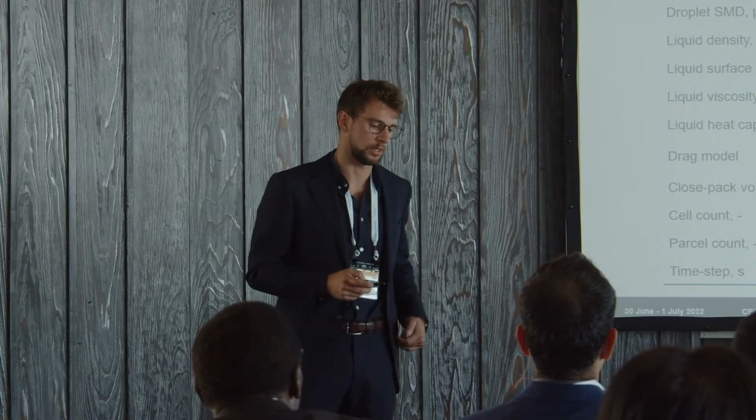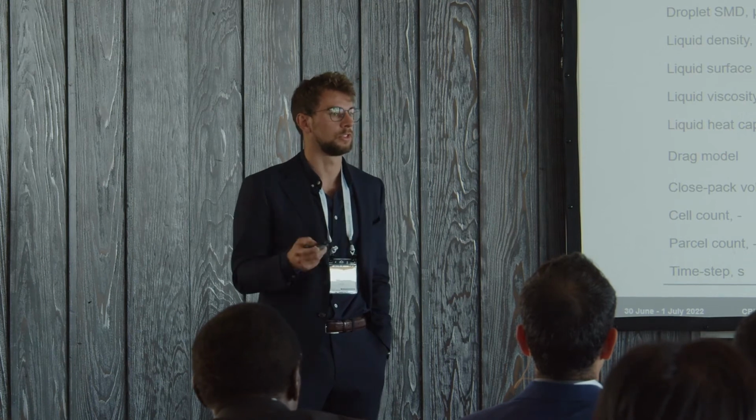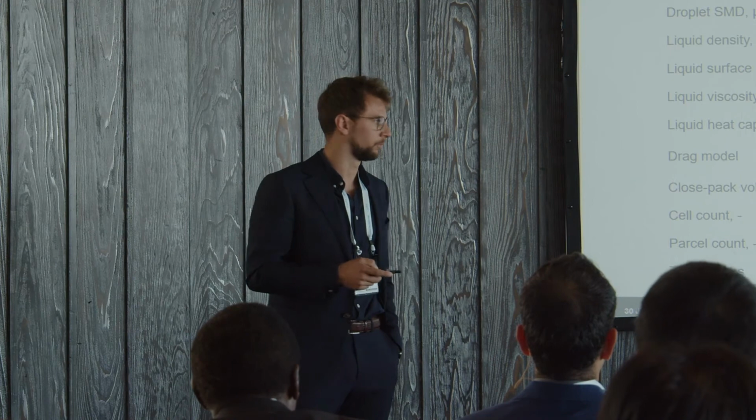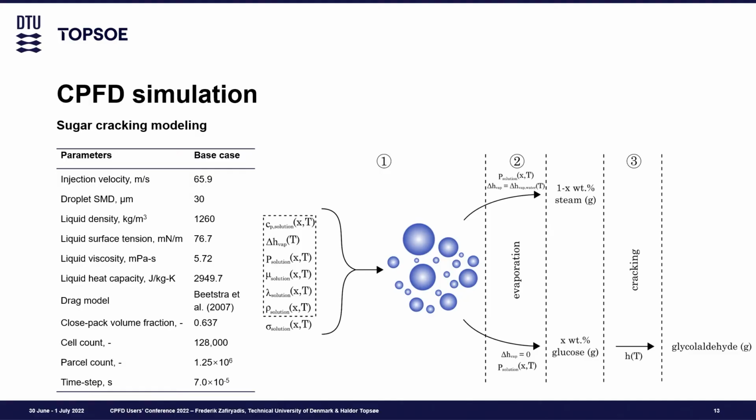It actually looks like how we do it in FCC, but in this case we don't have this assumption of instantaneous evaporation. So we know all about our droplet sizes, we know our inputs, our size distributions, velocities, everything like that. They're being distributed, evaporate, collision model, whatever, all that stuff. So that's fine, that's step one.